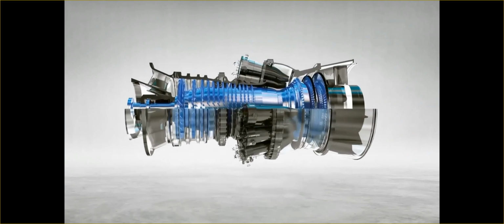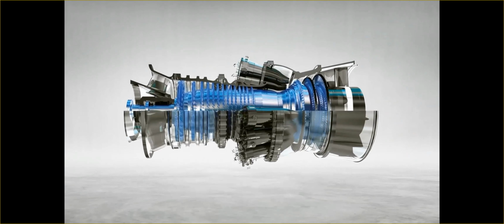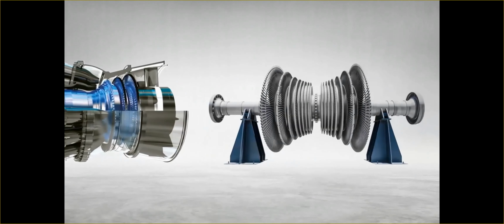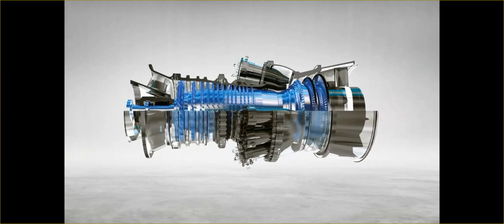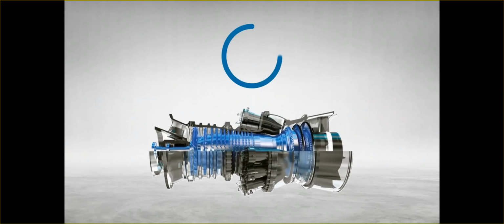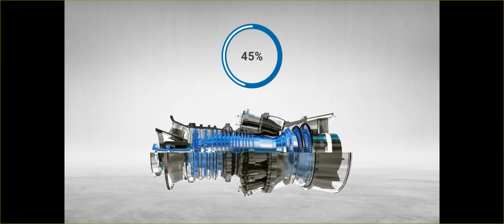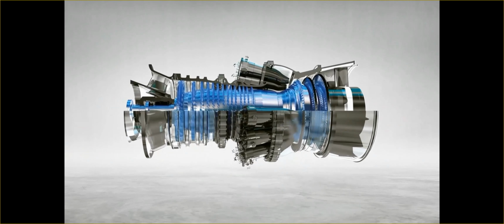In combined cycle power plants, gas turbines work in combination with steam turbines. The hot air in the exhaust of a gas turbine is used to generate steam for a steam turbine. This increases the power and efficiency of the power plant. Nowadays, the efficiency in a combined cycle has reached a remarkable value of more than 60%. And this is how a gas turbine works.